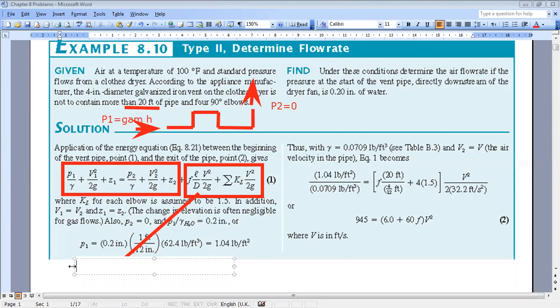And what we mean by major losses, this is due to the length of your ducting system, okay? And why they say they are major, because in general, any system, due to the length, will have losses induced. And these losses will be in general dominant over minor losses, especially if you have a very long piping system. So when L over D, the length of the ducting system over the diameter, is large, we can say that major losses will be dominant over the minor ones.